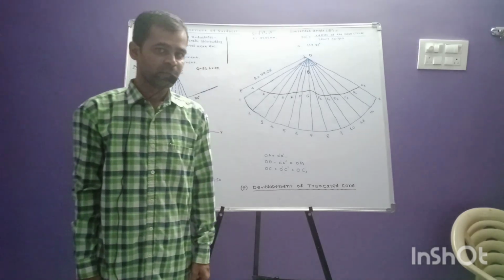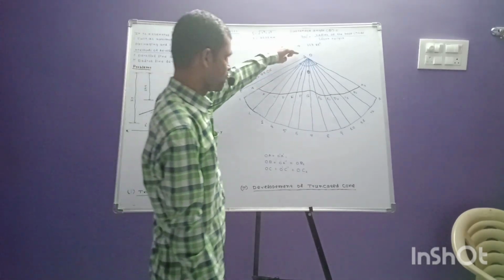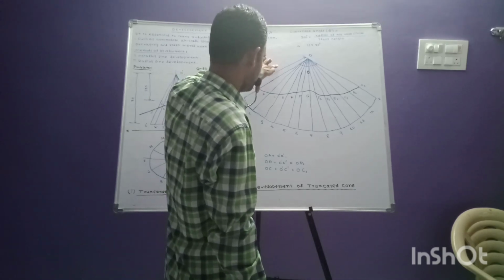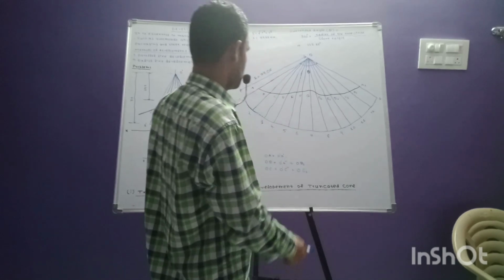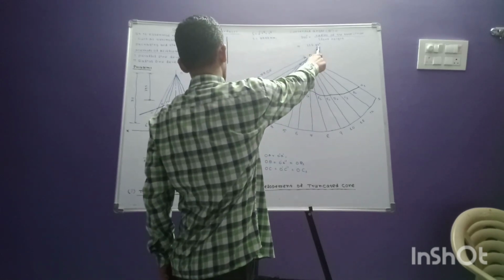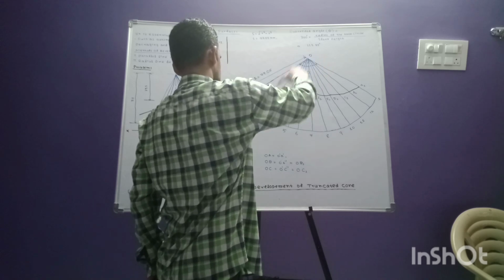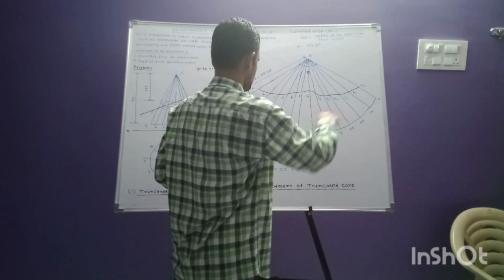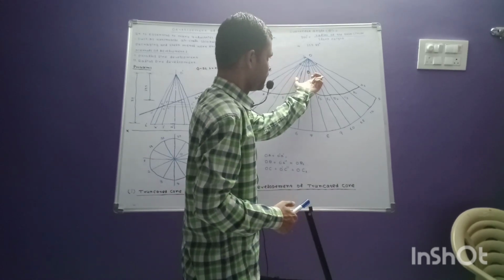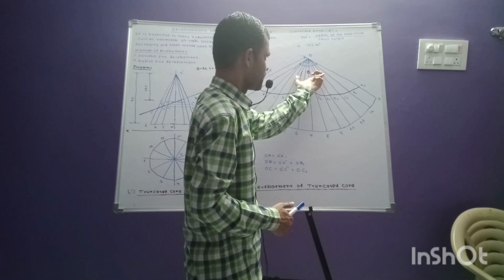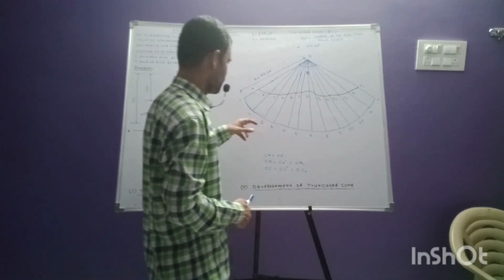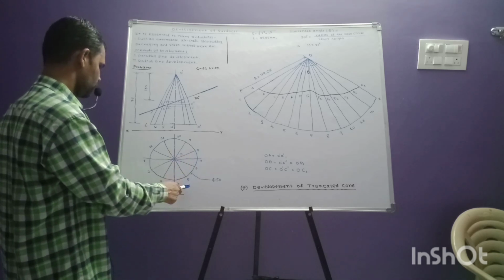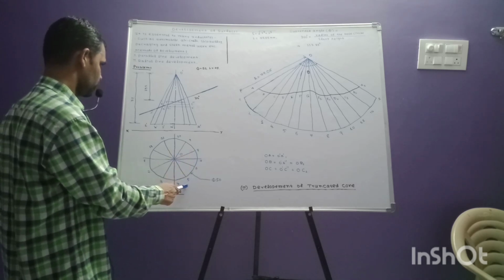So in the radial line development method, first we have to take center O, with slant height as the radius, and draw an arc. Theta, 113.85, is this portion, the sector angle or subtended angle, and we have to divide this sector into 12 divisions, since we have 12 divisions of the circle in the top view.